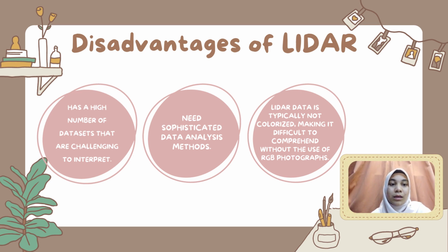Hence, it needs sophisticated data because high performance spatial indexing is required for speedy data access and analysis of LiDAR data. Due to its complexity, processing the data and spotting inconsistencies or errors demands a thorough understanding of the technology. Studies frequently produce their final products using only a small subset of the data.